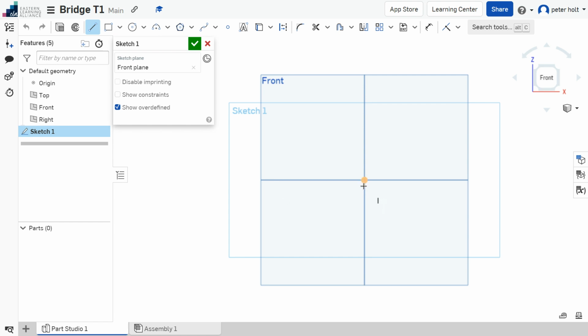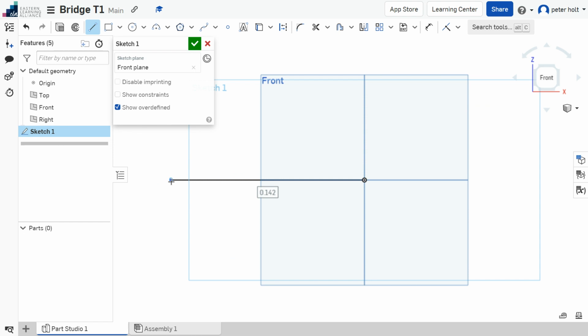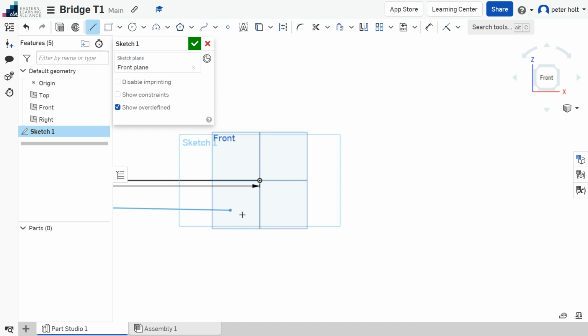So I'm going to grab hold of the line tool, and I'm going to draw a line out. Now, it doesn't matter how far I go. There's no way I can draw it large enough. I could zoom out and do it, but it's actually much easier if I just click wherever, just once with the left click, and then I can type in 5. Now, remember, we've set it to meters already. So 500 will be 5 meters. Now, I've gone from the middle of the scene, so I don't want 5 meters. I actually want 2.5 meters, because then I'm going to do the same on the other side as well. So that gives me a line that's 2.5 meters long.